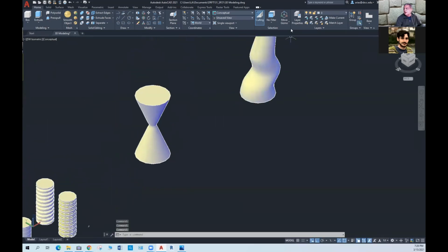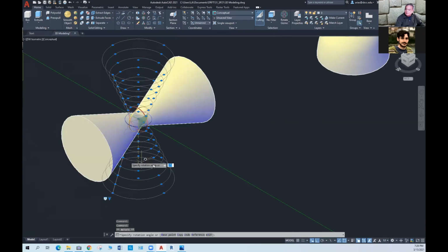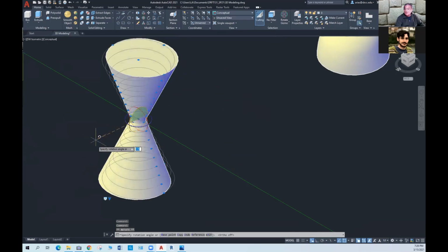And so let's look at this. I am going to select the gizmo rotate, or the rotate gizmo. Now I click on the 3D object, and we see the gizmo right there, located at the axis origin point of that particular object. Now, this is the rotate gizmo, means that I can use those 3 different coordinate axis circles to rotate the object in any of those directions. For example, the green. Now I can rotate the object on the green. See?